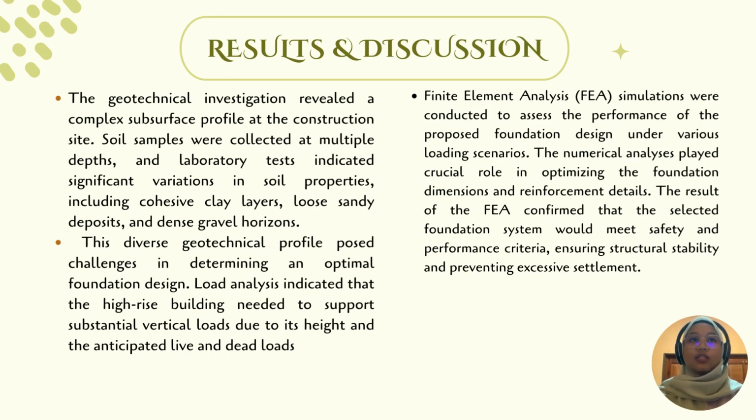This is the result and discussion of my case study. The geotechnical investigation revealed a complex subsurface profile at the construction site. Soil samples were collected at multiple depths, and laboratory tests indicated significant variation of soil properties, including cohesive clay layers, loose sandy deposits, and dense gravel horizons. This diverse geotechnical profile poses a challenge in determining an optimal foundation design.